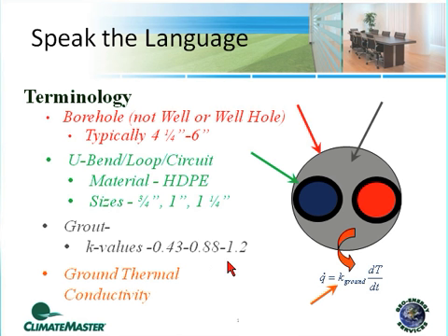Now, you can take this value even higher, up to about 1.2, but there are going to be more physical construction constraints that come into play here. Grout with a thermal conductivity of 1.2 has so much sand in it that it becomes very, very difficult to pump in a grout pump. And if that contractor's not set up for that, the grout will get stuck in all his grout piping and setup, and he has to break down all his equipment and wash it all out.